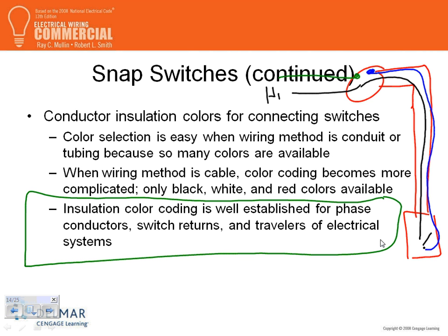If you have a cable that's in a conduit, you have to pull other than gray, white, and green conductors for your switches. If you have a cable, you have no other option. If you're wiring with cable, like we did in residential, I don't know if you guys remember that one. Here's my switch, and this is a cable. Remember, that's a cable. And here's my light. I'm wiring with a cable, MC cable, AC cable. I can't emphasize that one enough. Here's my neutral coming to the light, and here's my phase A, coming to this fixture.